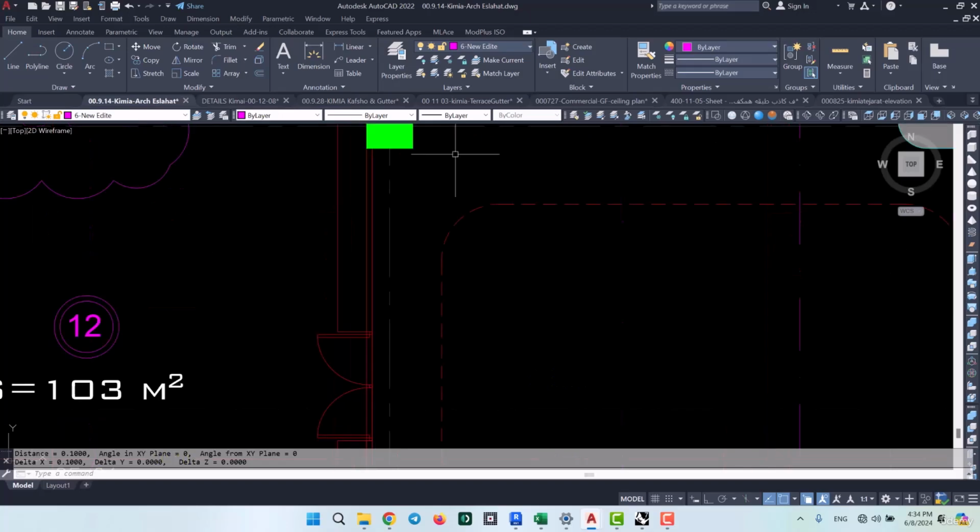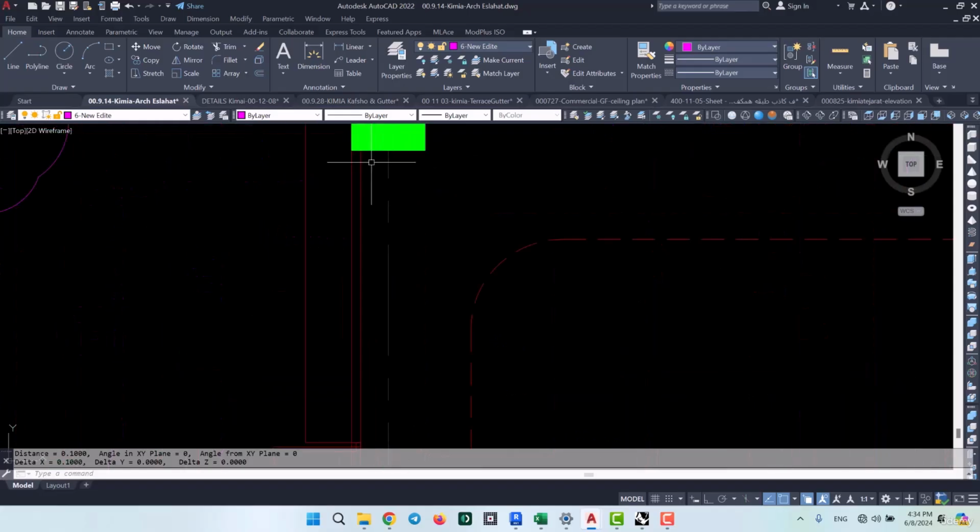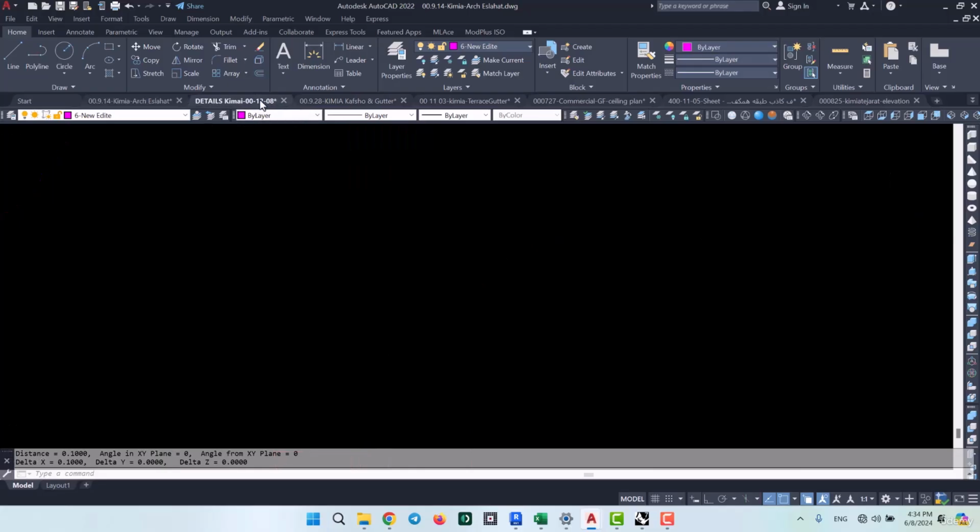But there's one thing that we're missing, which is the detail of these partitions. This one right here is a Phase 1 plan, and therefore we can't see any details for this area. We should either be given the details file, or we might have to directly ask the client what details should be considered for this. Because it's really not as simple as it seems, as we will be needing the glass thickness, the horizontal and vertical perspectives, so we could use for help.